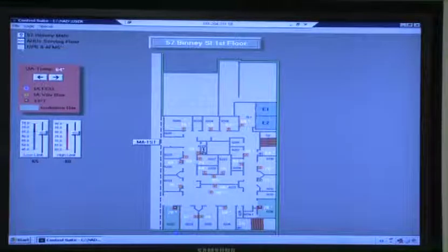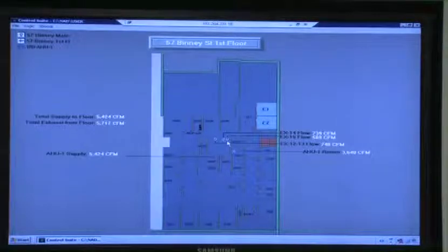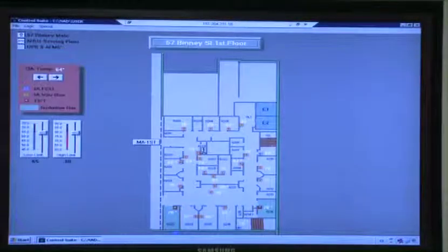No. Meaning, like this here, I need a screen like that for the sub basement. If you don't have one, meaning there's nothing down in the middle, then we don't need that screen. I don't think there's a, oh, there is. Is there a supply air flow station? Yeah, I believe there's a balance support that makes it. So I need the screen for the sub basement. So, going back to the first floor.